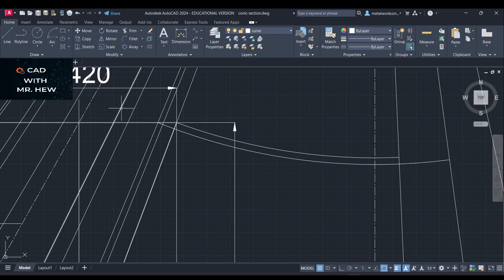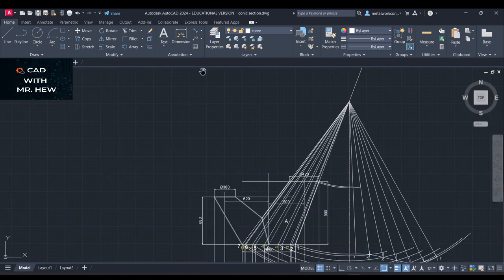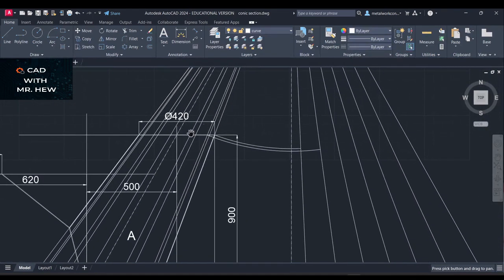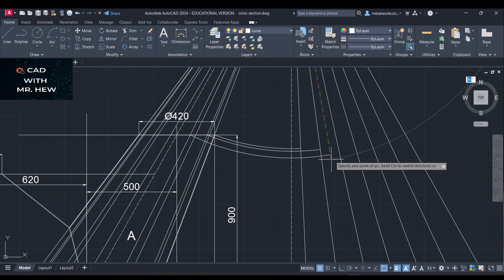All right, so we're gonna do 3, which is this line coming down, where it intersects this line. That is the point that we're gonna carry around. So we're gonna go up to the apex. Here, I'm gonna come around to this line. We're gonna do the same thing for the true length on the front elevation for 4, which will be right here, where this line intersects this line, okay?